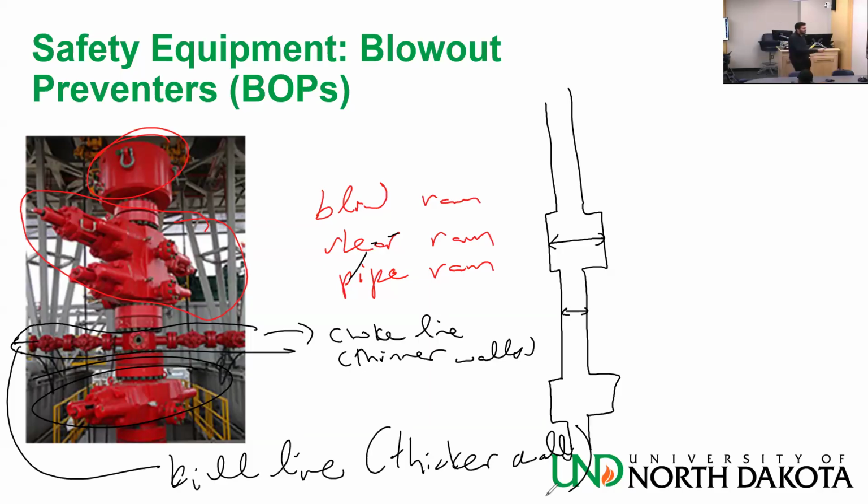It's like this part here, you see the hole, one is bigger than the other. The one that is smaller is the one that can hold higher pressure. So if you want to inject something down hole, you need to do it at a pressure, so you need to hammer the pressure. If you are choking, like the choke line, you are removing something, circulating out of the hole, and it's coming out at a lower pressure. It's just like the mud return line, but now the well is shut in. That's why I said SICP, you are measuring it from there. You are measuring the choke line, right? Got questions? No. Okay.